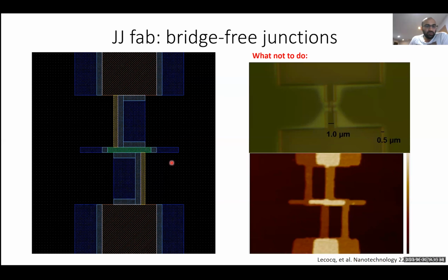And so you can quickly see that because of the large number of different doses to keep track of, to actually do this correctly, you need to calibrate a larger number of doses. And if you do it incorrectly, you'll end up with something that looks like this. So if you can see here, there's this region that's shaded a little lighter color. This is actually a natural undercut that's formed by a proximity effect.